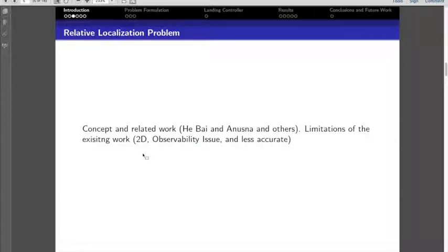So the issue is whenever range, because range is the sensor that we are using to update our states, right? So if you are flying around a circle, or if you are maintaining a constant distance, then that range measurement is constant and it is not giving you new information. Okay, so that's why the system becomes unobservable. And another thing is it is less accurate. We have seen that some trajectories will give you really, even if it is observable, the estimates are not good.